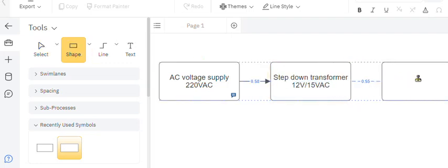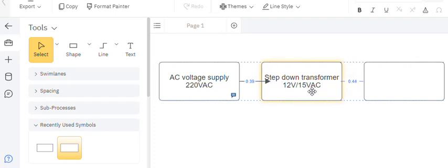So next stage after this, by the time the voltage has been transformed from high volts to low volts, then the next thing we want to do is to actually do the rectification. This is where our diodes network will be needed. So the rectification we are going to be doing here is full wave, or let me just call it rectification, rectifier. So the rectifier is a stage where the AC is actually converted to DC.